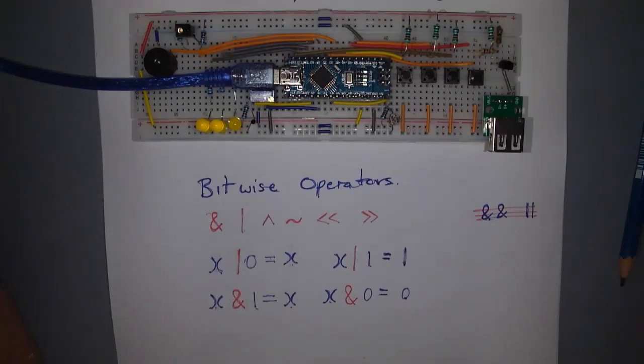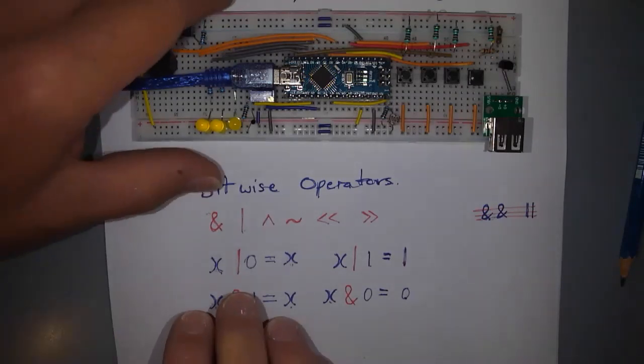If we go to the simulator, you can see I've got a function there, show count, and what it does is it takes a value and it shifts it left by 1 and puts it onto port B. So it's having a little explanation of what's going on here. Here's port B. Port B has got 3 LEDs on it. Okay, so let's think about this. We've got 3 LEDs on port B.